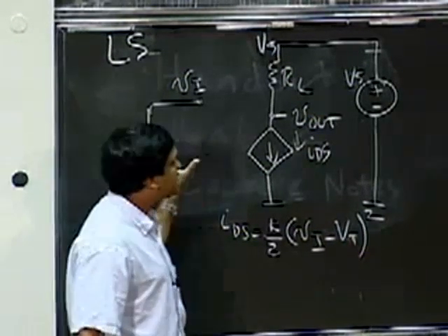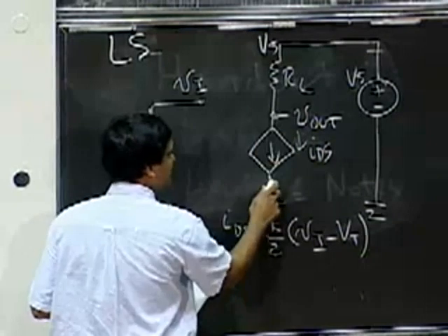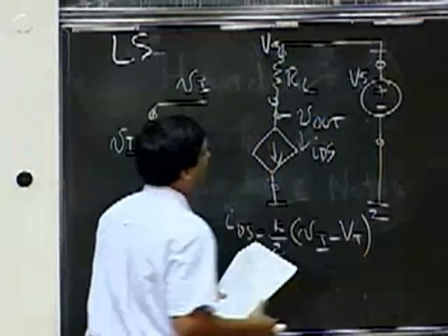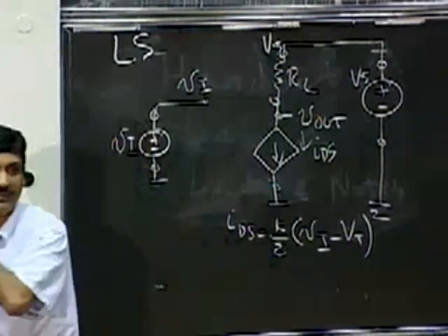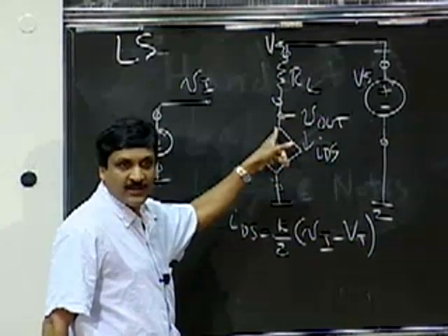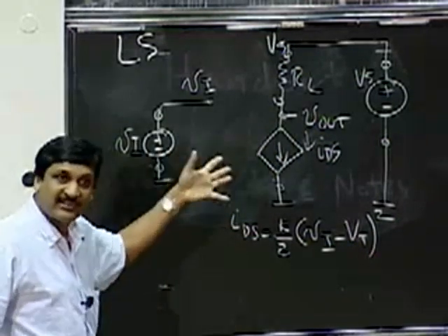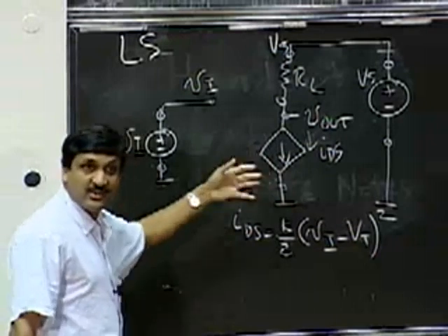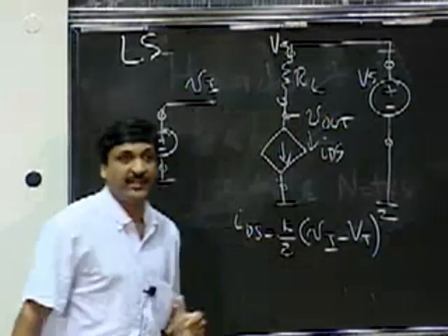And what I'm going to do is keep the same circuit, keep the same circuit connections, and simply pull out the large signal model for the element and replace it with the small signal element model. Okay, and by their nature, the small signal models are all going to be linear. So what I'm going to be left with is a linear circuit with simple linear circuit elements in there.